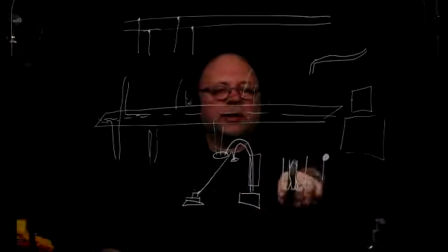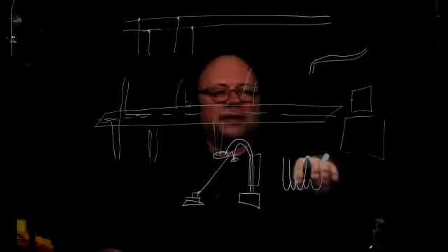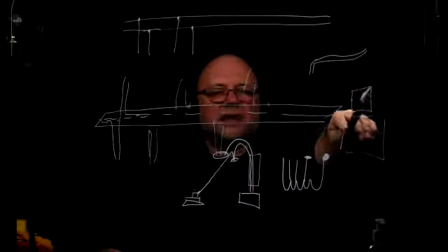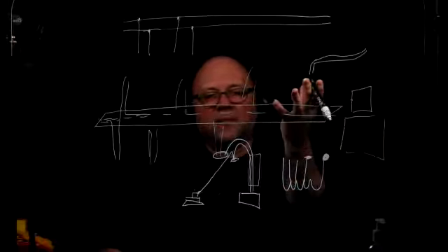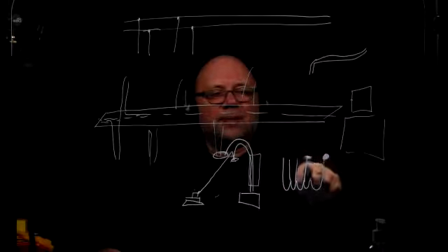If there is a tap that says 1 watt or 1.25 or something like that, it's considered 1 watt. Or 2, or 1/4 of a watt, or maybe 4 watts or 6 watts. Which means that if that speaker is tapped into this 1 watt tap, and the main amplifier is running at full volume, it is going to grab 1 watt out of that.